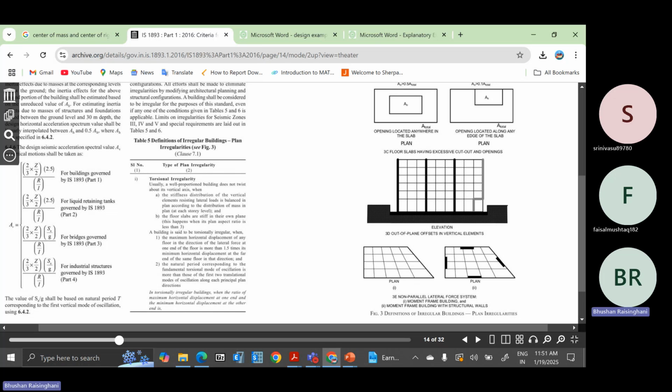However, when it comes to mezzanine level, mezzanine floors, we cannot take them as a stiff or rigid diaphragm. So we have to treat them as not part of the lateral load resisting system, because mezzanine slabs that are only up to 3 or 4 grids will not take part in lateral load resistance. So we don't take them as part of LLRS. We don't define them as diaphragms. We take them as slabs. So we will design them for gravity cases, but we will not use them to transfer the lateral forces.